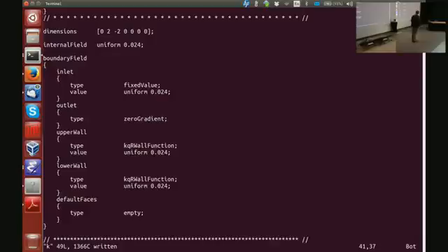Okay, but this is also quite boring because if I have 200 patches which are all walls, I don't really want to do it like that. So what I can do is I can say, give me all the patches that start with something and end with wall. So rather than writing out the full name of the patch, I will use a regular expression. Just for a laugh, I will try and guess how it's done.